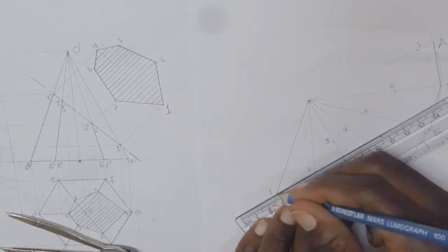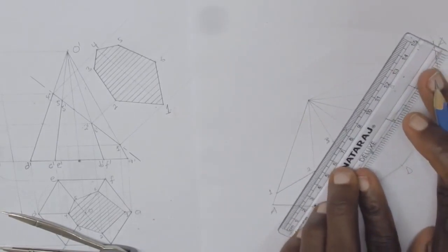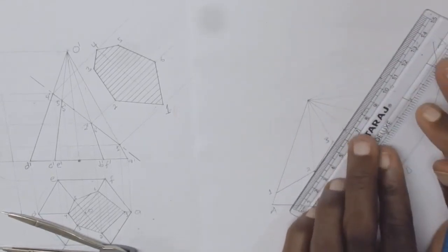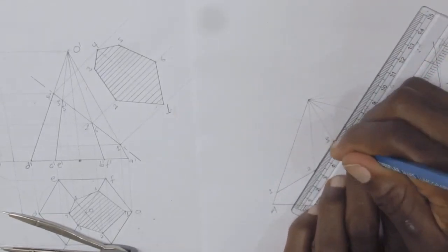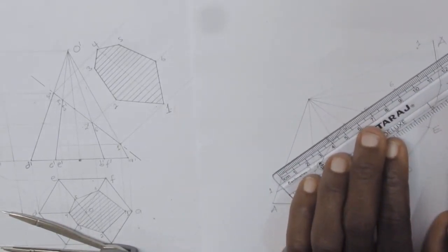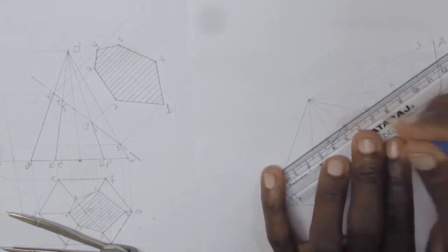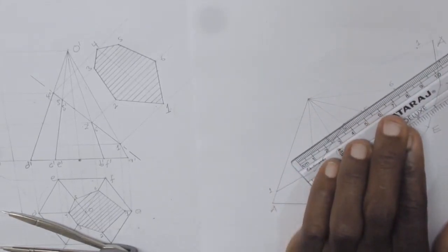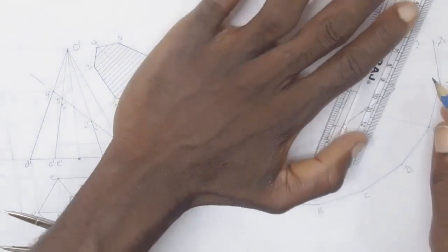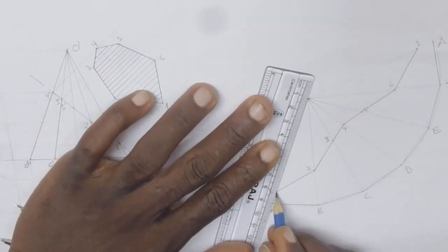We connect all these points with straight lines. Okay, so these straight lines here, as we connect them, represent the lines that make up the truncated surface. So those are the lines we have here. Right, so with this, we finish connecting them, we see that we have the development of the pyramid.